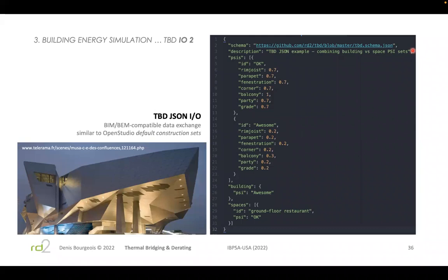But it may be, in very rare circumstances, unable to identify what the nature of a thermal bridge is, because what could be perceived as a wall is in fact a roof, or vice versa. So on one hand, we had a need to customize each of those edges potentially. And so how can we do this for 300 or 1,000 edges and still allow users to edit some of those, hopefully in a semi-automated way, so it's not a huge burden.